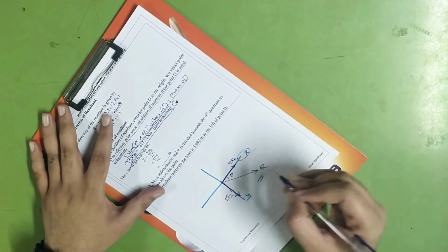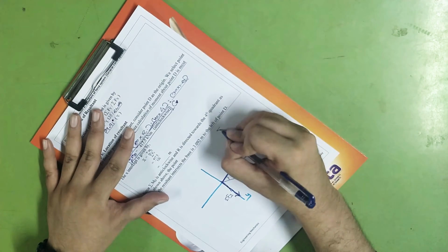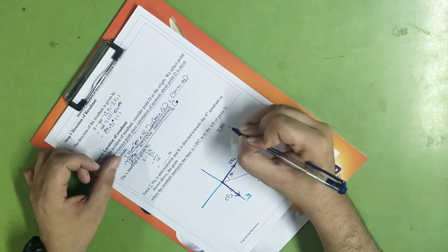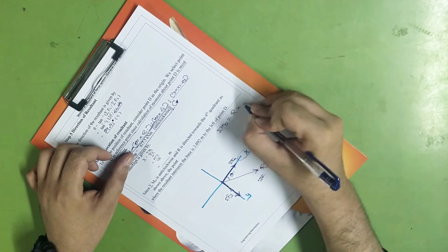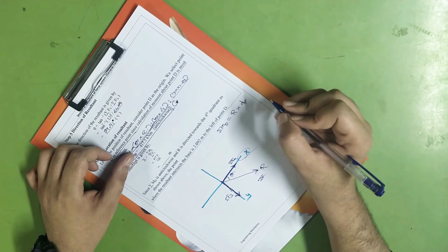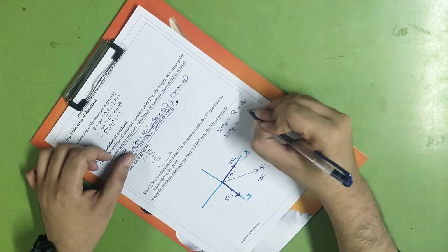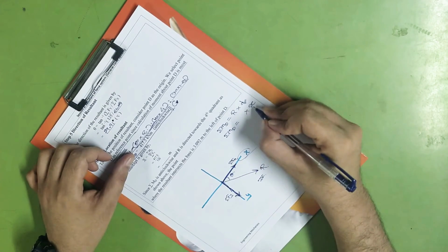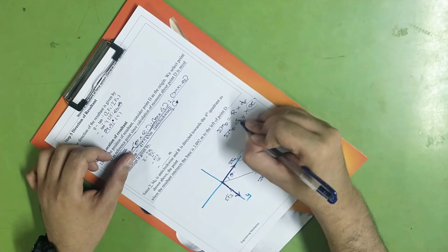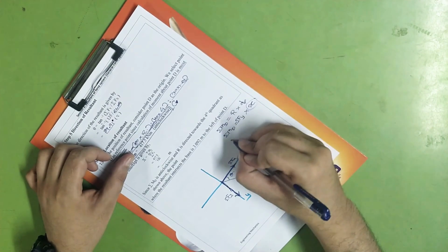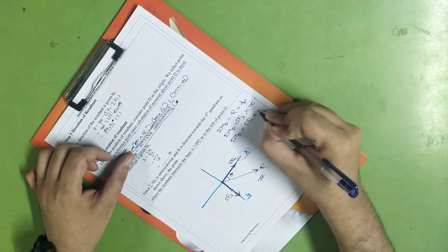Now, as explained last time, Varignon's theorem can be used in 3 different ways. First, the summation of moment about any point, since in this case we are taking D, will be the same. Summation of moment about D is equal to R into d, where d is a perpendicular distance. Next, summation of moment about D can be equal to, suppose I want the X intercept, then since the perpendicular to X is Y, I say summation of Fy into x. And in the third way, similarly I can get summation of Fx into y.